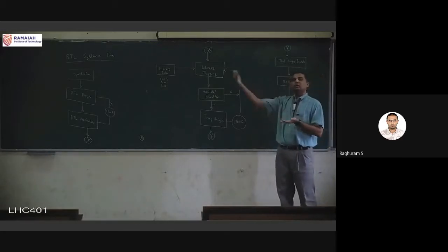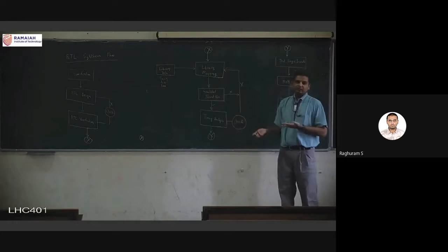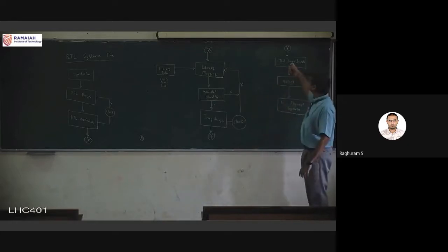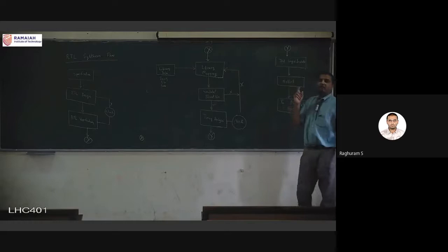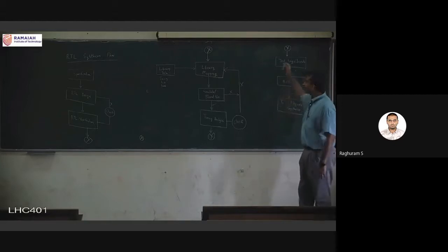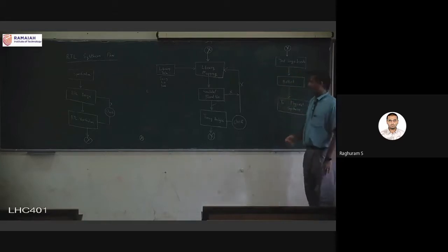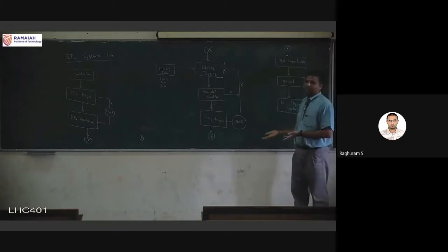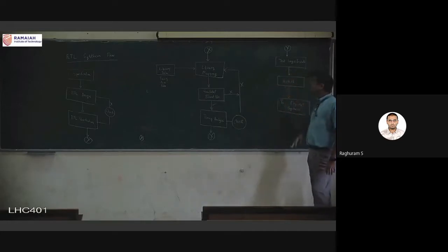After that, you can go for mass production. Until that, they don't go for mass production. But this is the key point for post silicon. After the actual silicon is there, there are many things that they check, but one of the most important things is test for fabrication errors. And that is also inserted as part of the front end VLSI design, because these are also logic gates. Anytime you're putting logic gates, you have to put the test logic also. Okay, and then you get a new netlist.